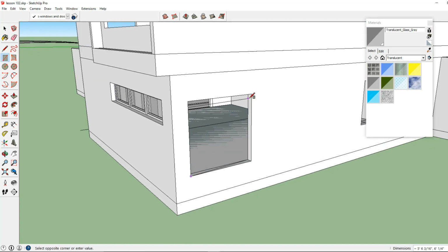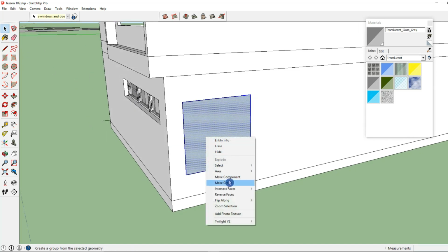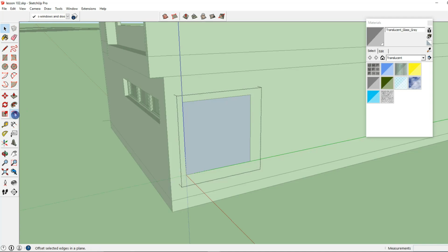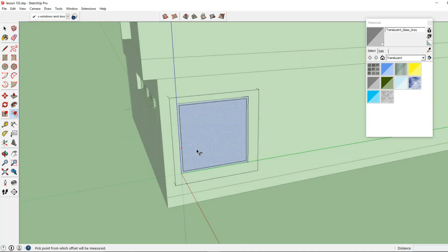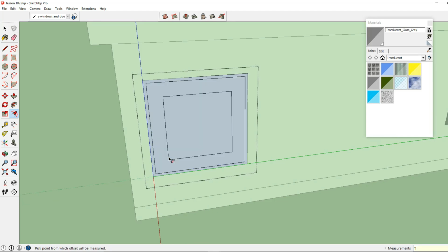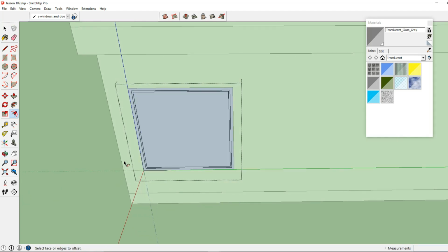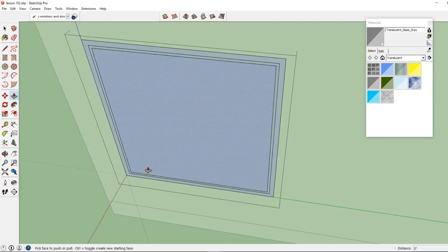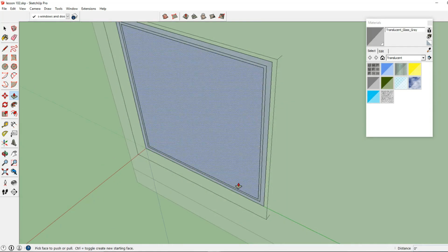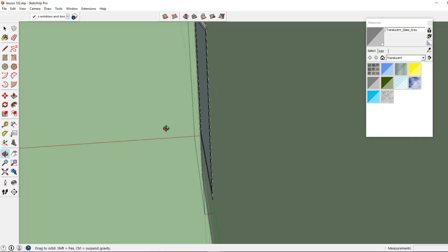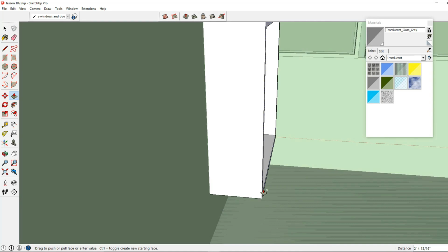So now we're going to make a big picture window here, and I'm going to use those same parameters of 2 inches and 1 inch just for my window frame, and just a little window ledge there. And here we go. I'm going to push this in 4 inches, and if we want to see that, we can go in here.